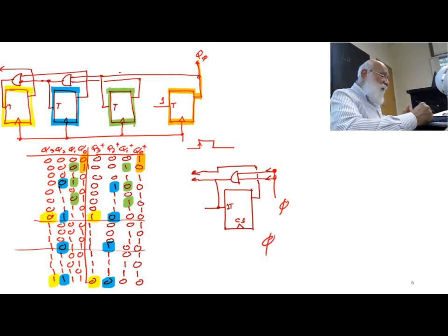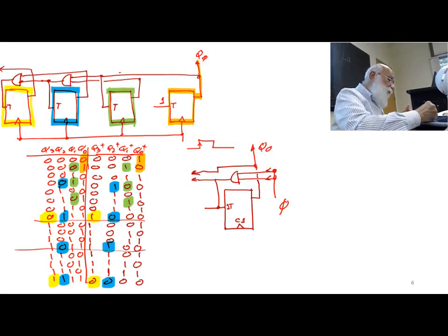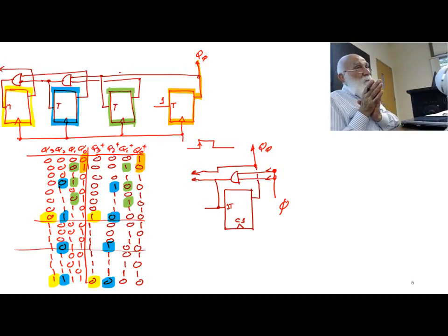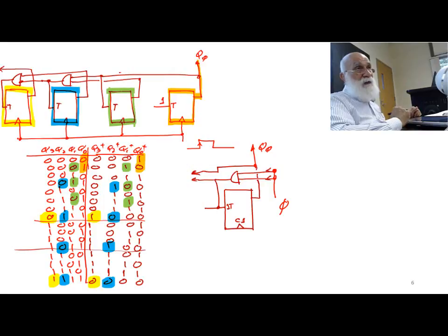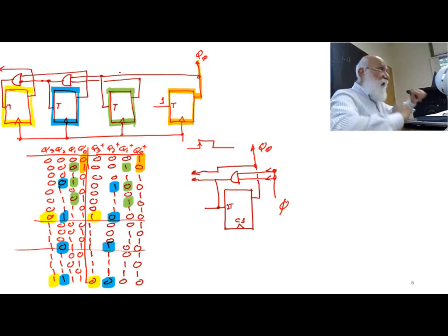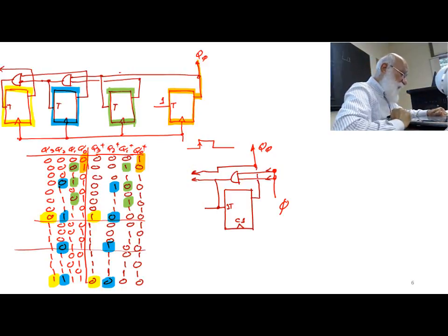The 0 on the AND gate of the rightmost flip-flop, this is bit number 0, Q0, propagates all the way 0 to all the AND gates. What it means is, whatever you clock it, it's not going to change. Okay? And therefore, I am using this as an enable for my counter. Okay, that's one thing.